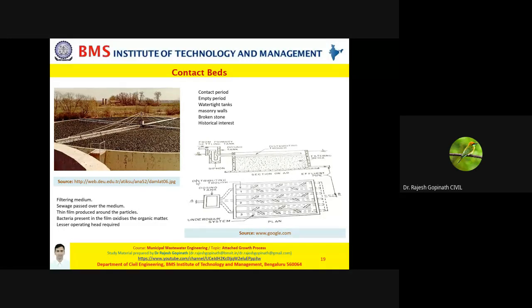The last stage is called resting. After you empty, the contact bed is allowed to remain at rest for at least 6 hours. So you're allowing atmospheric air, you're allowing oxygen to enter. This is as simple as the construction and working of a contact bed. I would also remind you that contact bed and intermittent sand filters are not part of your syllabus, but the objective of covering this is so that you appreciate what technologies existed before.